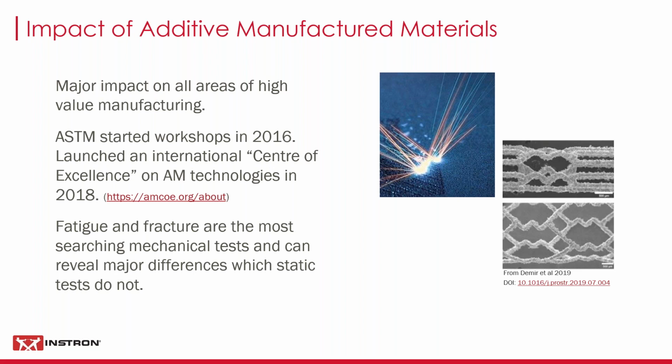So I know people who can make you a piece of solid additive manufactured 316 stainless, and it will give you an identical basic strength test to a piece that was rolled or drawn as wire. However, if we put that into fatigue, then we will immediately start seeing quite different behavior. So it's something to bear in mind if you're thinking about this area. Don't just believe the basic measurements. Look deeper is always what would be my advice.